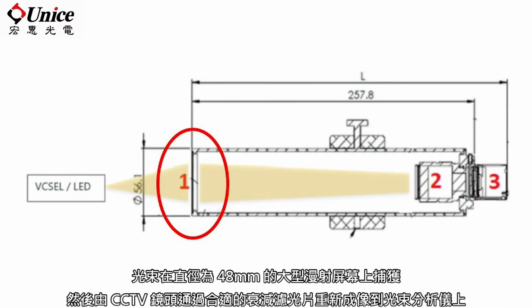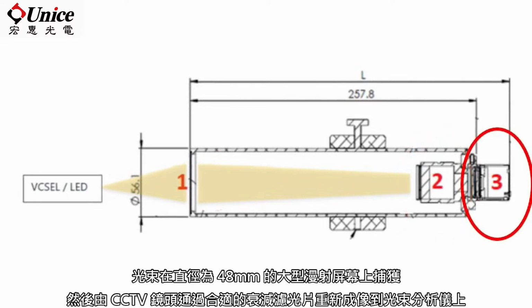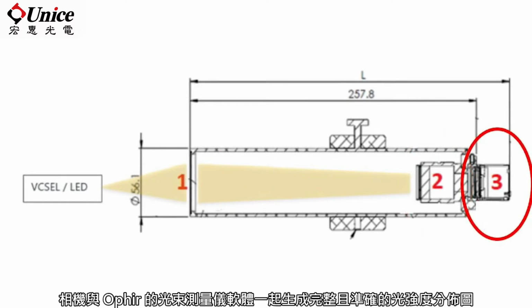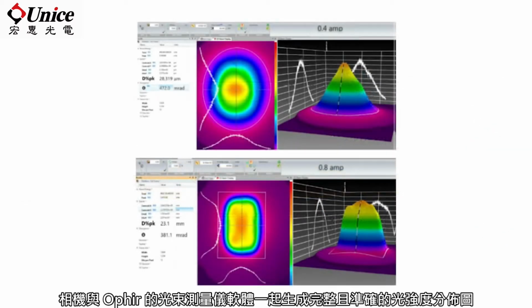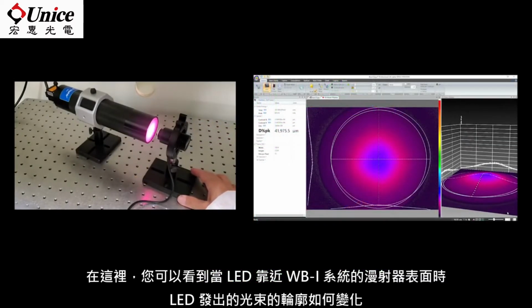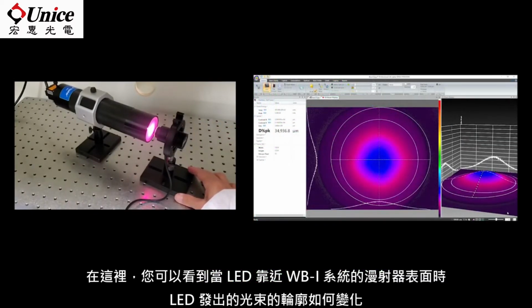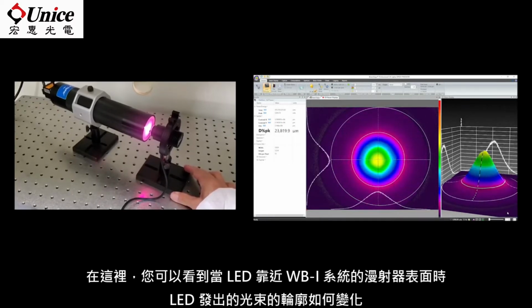Beams are captured on a large 48mm diameter diffusive screen and then re-imaged by a CCTV lens through suitable attenuating filters onto the profiler camera. The camera, together with Ophir's beam gauge software, produces a complete and accurate mapping of the light's intensity distribution. Here you can see how the profile of a beam emitted by an LED changes as the LED is moved closer to the diffuser surface of the WBI system.